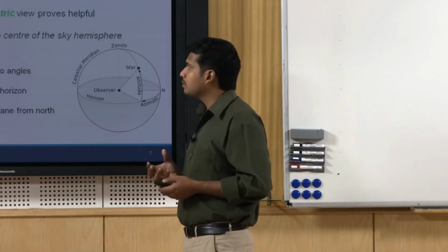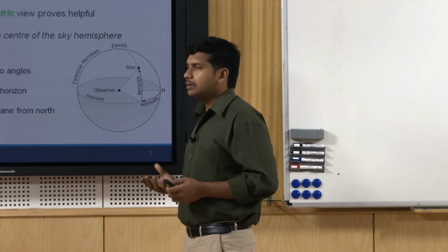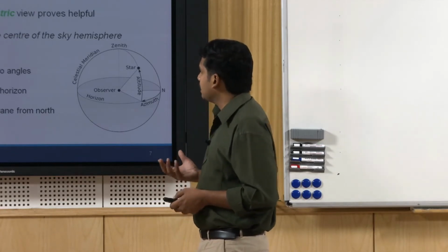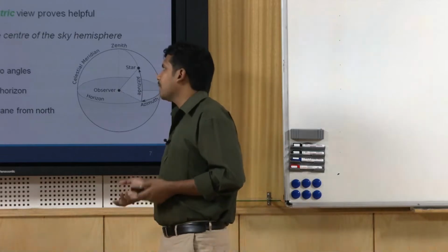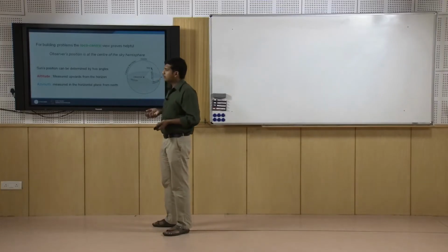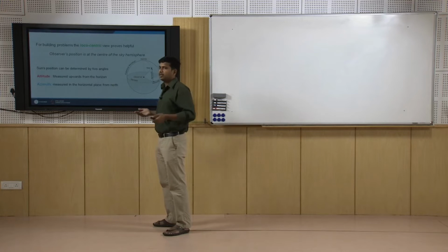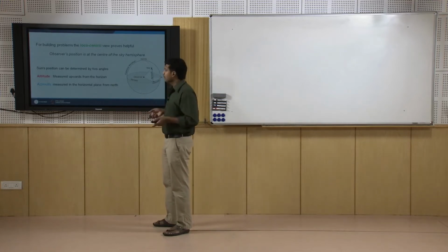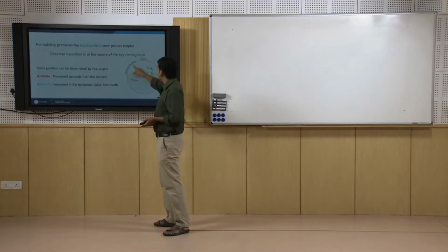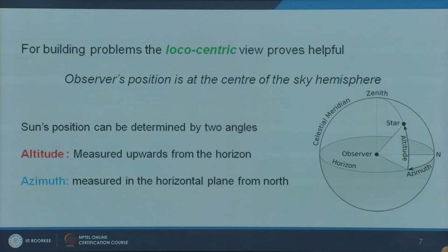If we have to derive some implications of the solar geometry on our design, we have to start mapping the sun position. The first step is to get into a lococentric theory and get 2 typical angles to map the sun's position on a 2-dimensional plane. The sun is a 3D moving object, so from that you derive 2 typical angles from which you can project. It is a trigonometric projection.